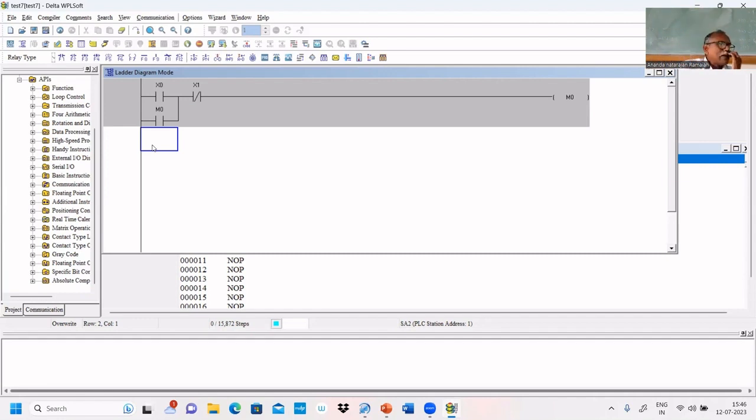You stopped in the middle. You cannot drain because when you turn on the outlet valve, the tank is full. But you stopped in the middle. The tank is not full. How can you open the valve? You cannot open the valve. So those provisions we have to provide in the program.